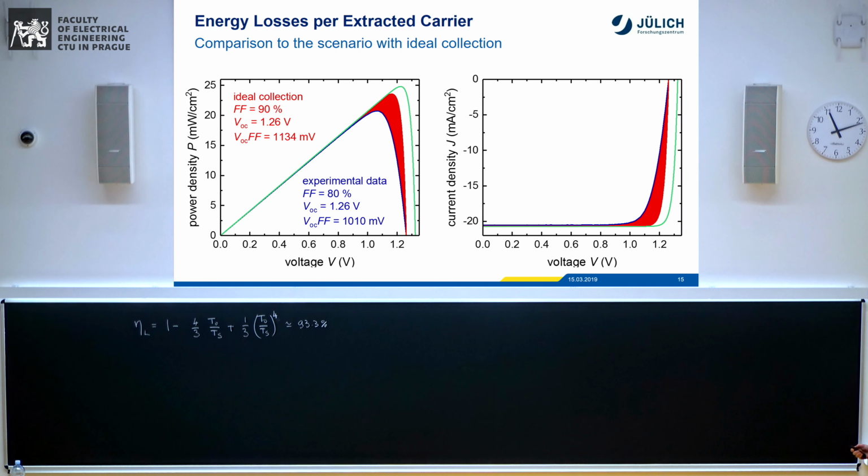Okay, now let's first look at this difference. So this is the same VOC, but perfect fill factor. Yeah? Perfect fill factor is defined by 0 series resistance, infinite parallel resistance, and an ideality factor of 1, which maybe you can debate about. Yeah? And you see that there's actually 10% difference. So that's actually quite a lot. Yeah? So there's a lot to gain there, surprisingly much.